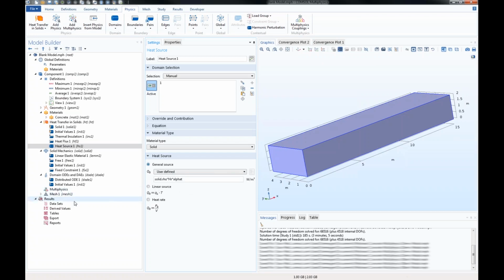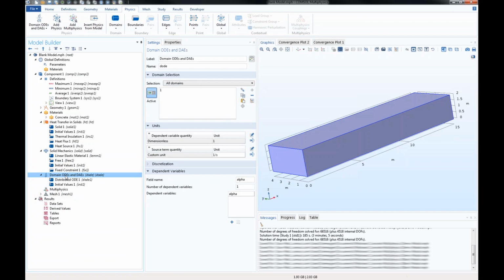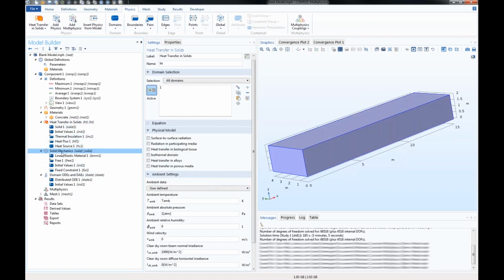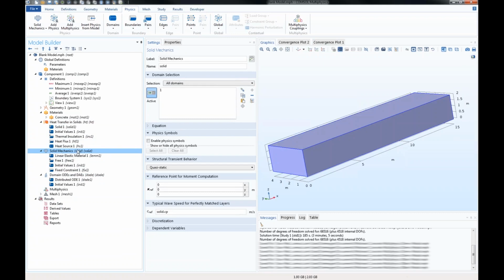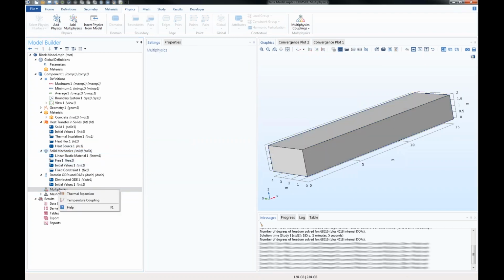What remains now is that multiphysics effect. So I have coupled this curing equation with the heat transfer, but there is the solid mechanics part. Granted, this being a small deformation problem, the solid mechanics doesn't have any effect back on the other two, so I could first solve those two and then use that result to do solid mechanics, thermal expansion, but I could also solve them all together.